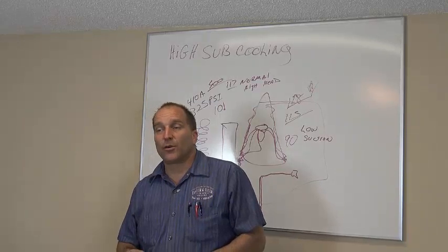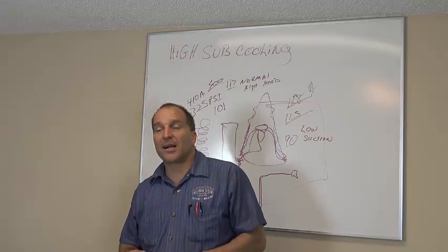Okay? What if you got a dirty evaporator coil? Is that going to cause a high subcooling?